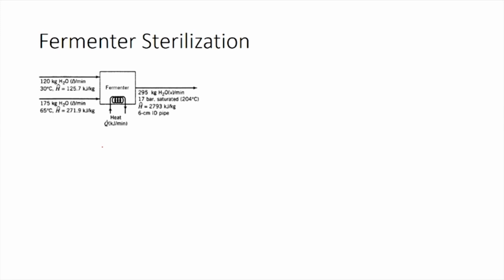First, we need to identify the volumetric flow rate. How can we convert the mass flow rate that we have into volumetric flow rate? The steam tables give us information not just about internal energy and enthalpy, they also give us specific volume. Using specific volume, we can convert the mass flow rate into volumetric flow rate.